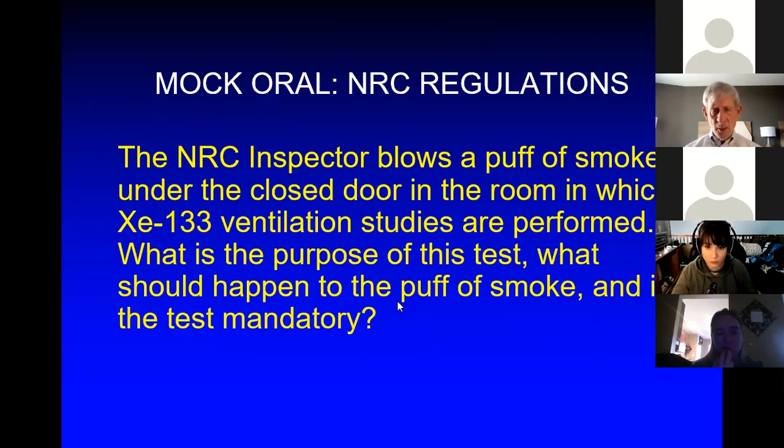This smoke test, I don't know if you've ever heard of this or not, but the state or the NRC inspector comes in and says, where do you do ventilation studies? You point out the room, he closes the door, he's out in the hallway. He has what's called a smoke gun, and he blows a puff of smoke under the door. Now, what should happen to that puff of smoke? Should it go under the door and into the room? Should it be blown back out in the hallway? What should happen to it? Should go under the door.